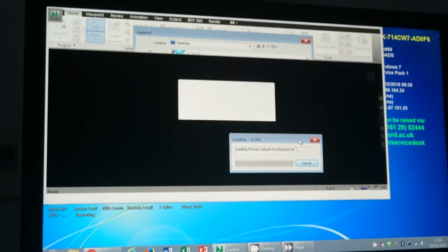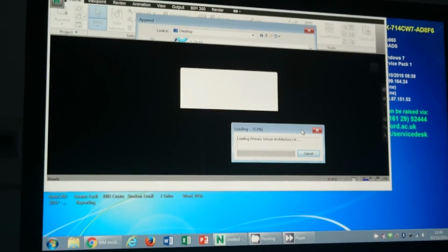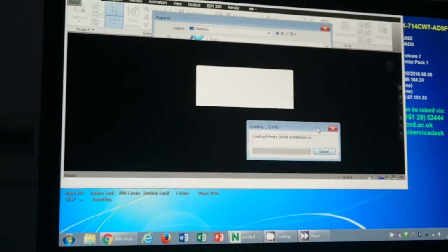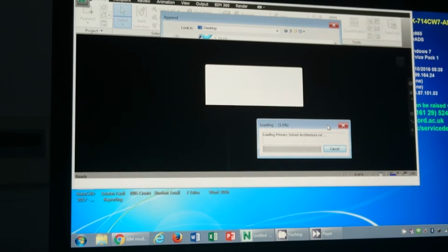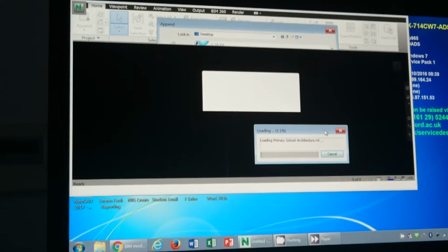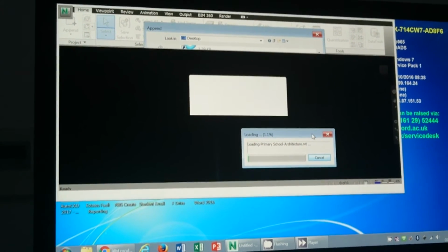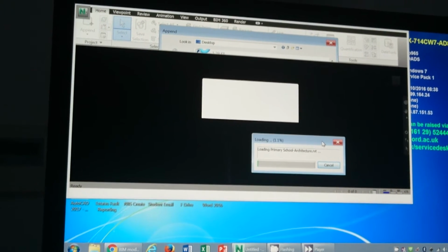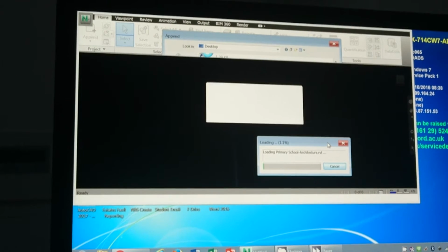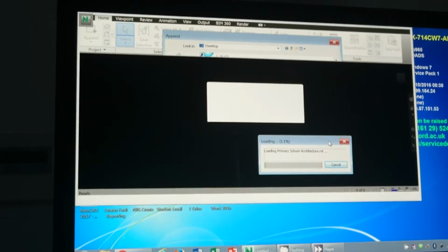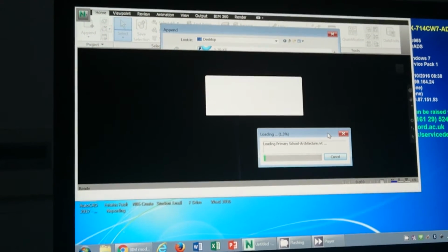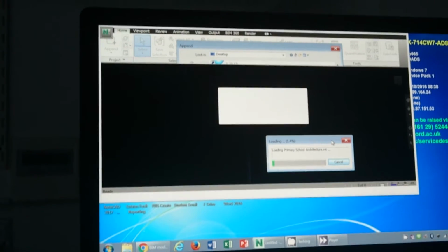So what it means is, you've got three types of Navisworks files: NWC, NWF, and NWD. I don't remember what's the difference between NWC and NWF, but NWD, for instance, is a standalone version. So if you have something, I'll show you some model, and you want to save it in a file and send it to somebody else, you're always using NWD because it has everything in the file. It will not be looking for connection.